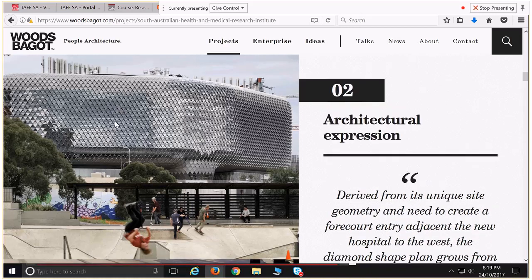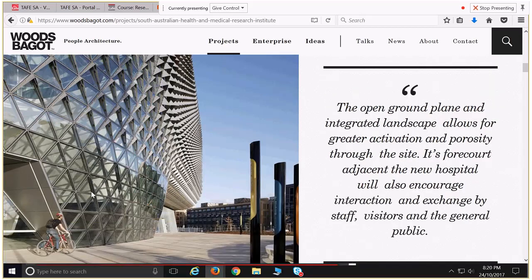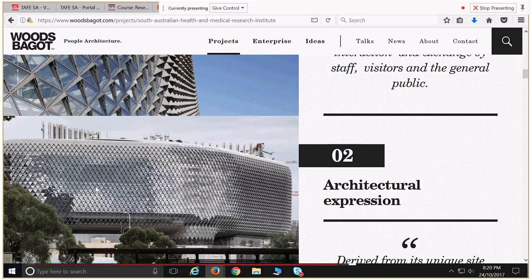That is curtain wall glazing. I guess, essentially they're using what we would refer to in this lecture as storefront glazing. So we've got our frames, but what they've incorporated in their curtain wall glazing are shading caps over the top of those triangles to provide the right amount of shading for that elevation. So to make it more solar passive design, still enable that curtain wall glazing to get lots of light in there for use during the daytime, and it ends up being a beautiful looking building for that.